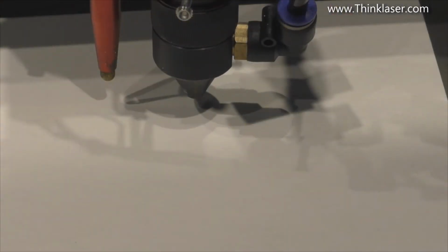Okay, now I'm going to scan two images on this page, and I'm going to give you a clue. They're both going to be scanned at the same speed and at the same power. Power is about 4 watts coming out of the tube, minus the efficiency of all the mirrors and the lens, so there's probably only about 2.5 to 3 watts arriving at the paper surface.